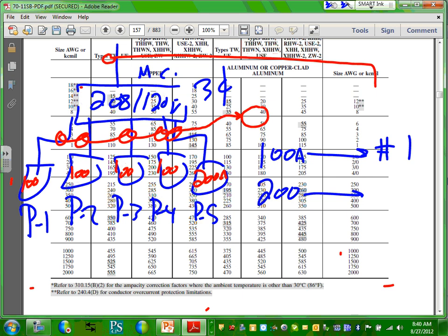For 200 amp, number 3/0. We're going to the 75 column here though. Is that 3/0? 3/0. Done. See how the sizes change? What was the size that we came up with before? We came up with number 1. Number 4, see how much smaller. And number 2, we moved up to 3/0. Why? Residential loads don't consume a whole lot of power, so they allow you to have a smaller conductor here.